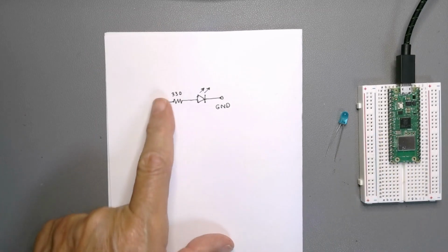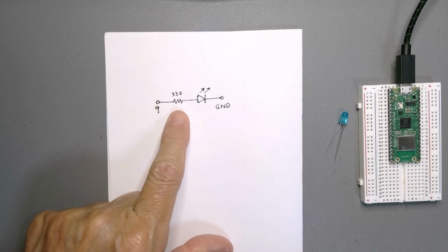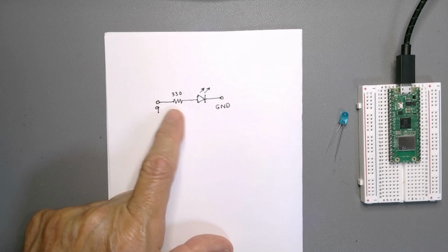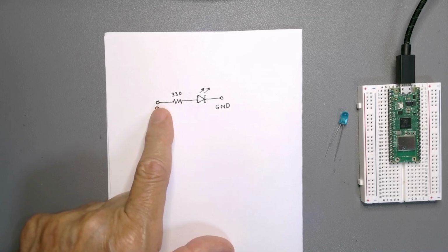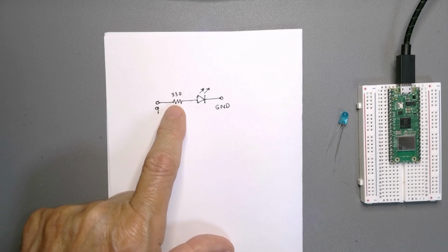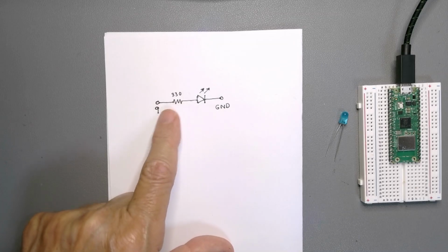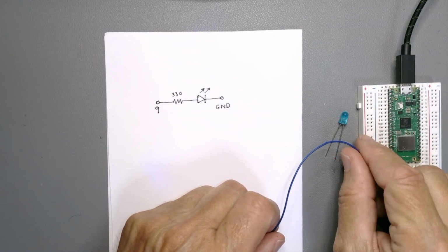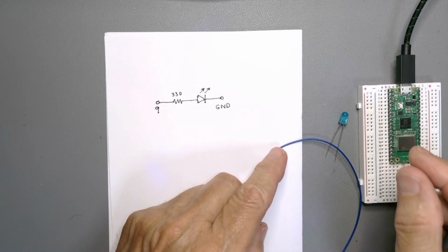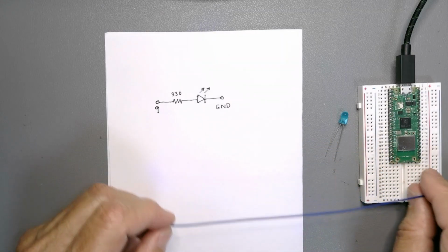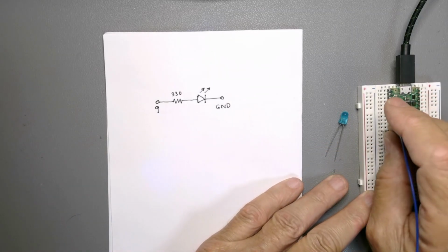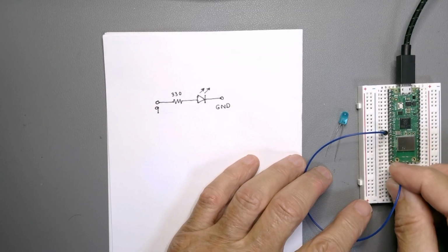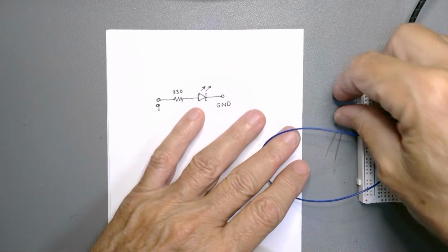Now, when I create a circuit that goes from one of these pins, this value can be either high or low, or 3.3 volts or 0 volts, depending on how we program the Pico. I usually try to use a color other than red and black. Red usually means it's connected to a positive voltage. Black usually means it's connected to ground. So I'm going to go from 12 on the left-hand side as I indicated. And now I can go to any of these rows right here. Just going to randomly pick one there, 23.